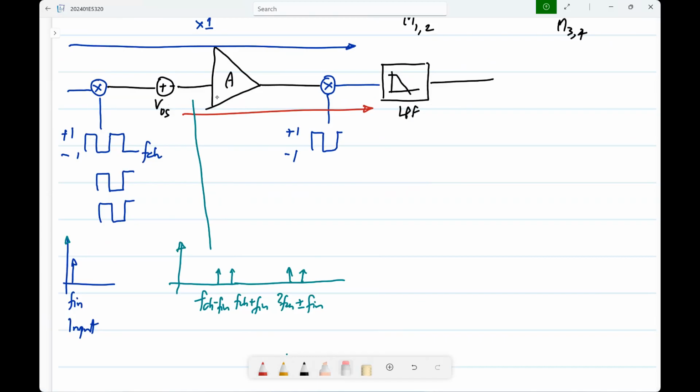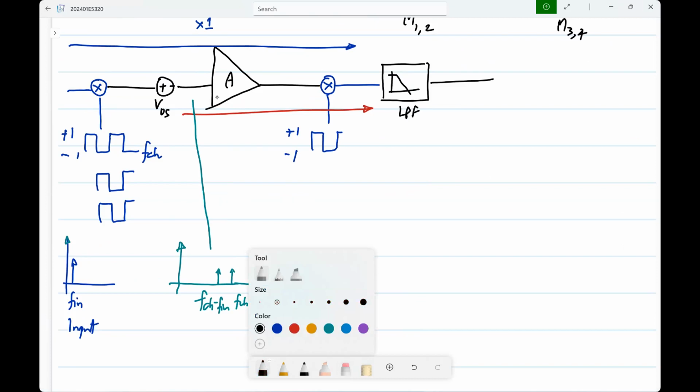There are many engineering details to make sure that this works correctly, because what was earlier a DC picture has now become a transient picture, right? But with this, you can get very low offsets. Without this, you cannot get offsets in the, let's say, tens of microvolts and so on. Okay. So to have that, you will need some dynamic technique like this. In fact, as the digital switching has improved, you can use dynamic techniques for many things. So I will just give an example since we came to the topic, but this technique is called chopping.